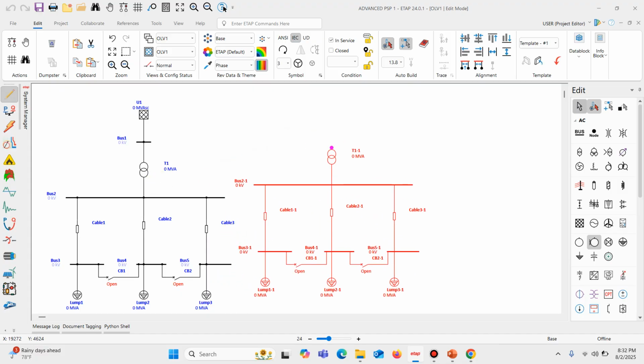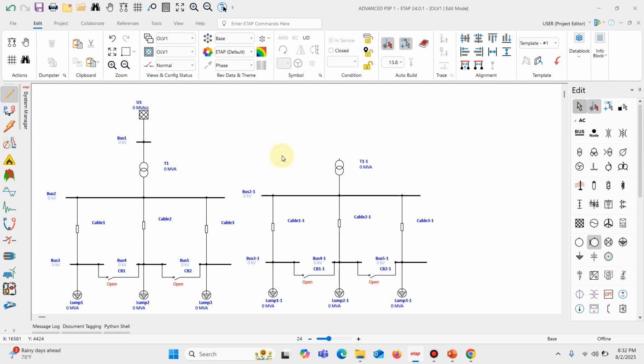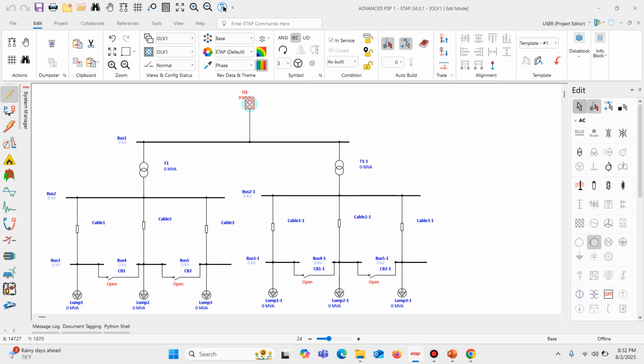So I can bring this over here, and then I can expand this bus bar, connect this transformer over here. You can bring the power grid to the central source. Okay. So now we've been able to create a bigger system. We are making the system much more complex. We can introduce an alternative source of power on this bus bar. We can put a bus coupler here just for expanding.